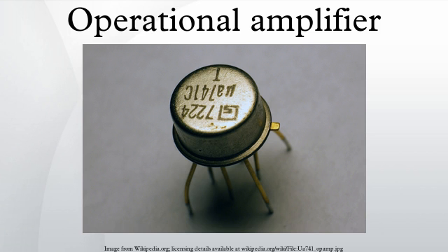If the inverting input is held at ground directly or by a resistor Rg, and the input voltage Vin applied to the non-inverting input is positive, the output will be maximum positive. If Vin is negative, the output will be maximum negative. Since there is no feedback from the output to either input, this is an open-loop circuit acting as a comparator. The circuit's gain is just the AOL of the op-amp.